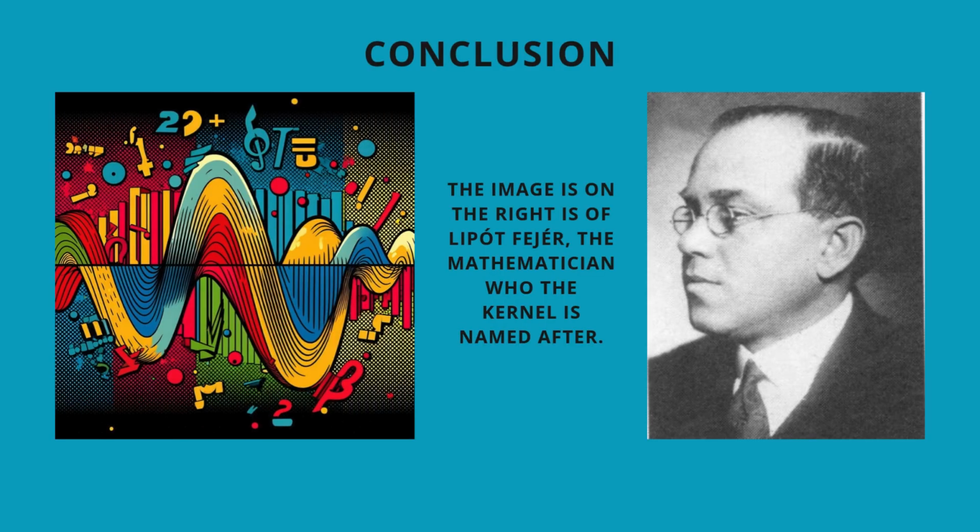In real-world signal processing, we often deal with signals that have abrupt changes, edges in images, transitions in communication signals, or sharp attacks in audio signals. The Gibbs phenomenon can introduce artifacts like ringing along sharp image edges or tonal artifacts in audio.